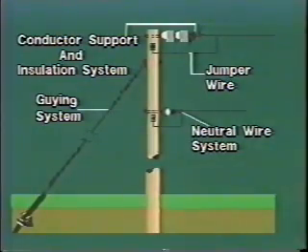When the conductor angle ranges between 60 and 90 degrees, two assemblies of dead-end insulators are used. The conductors are dead-ended into the pole and are joined together by a jumper wire, which carries the current between the two legs of the dead end.